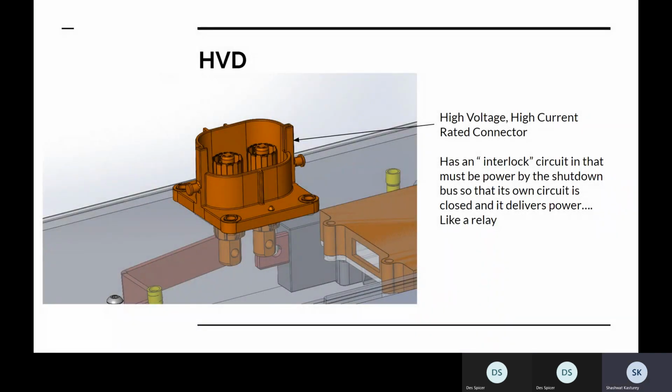Talked about the HVD a lot. It stands for high voltage disconnect. There's a lot of engineering going on with this connector in particular. There's a slip fit interference going on with those poles there. It's a pretty complex plastic construction, pretty rugged. It has those little nubbins on the side so you can latch to it.